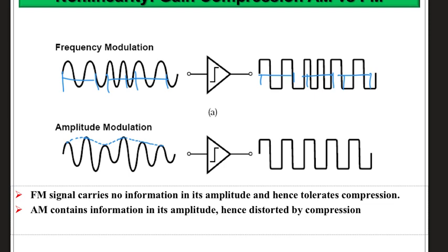This is one of the main advantages of frequency modulation versus amplitude modulation. Try it yourself. For example, some radio channels here in Qatar are broadcast both in AM and FM. Try for the same radio channel to listen to the AM and go, for example, through the highway of Lusail, the one that goes through south of Lusail, west of Lusail. That one goes under an underpass and then up, and then underpass and then up in many places. You will see that the AM signal gets really bad when you go through small underpasses. If you use the FM, most of the time it's maintained. Of course, unless you go through a long tunnel. That's a different story.